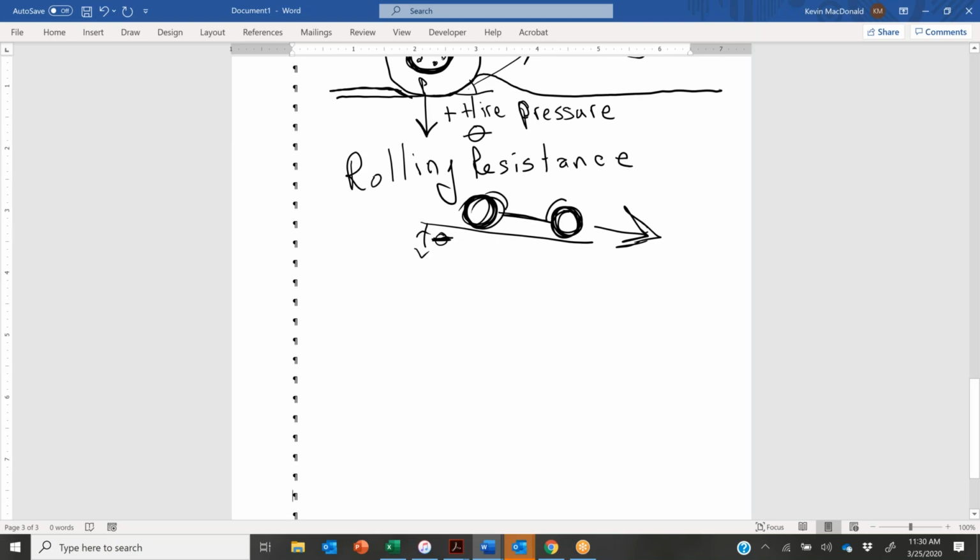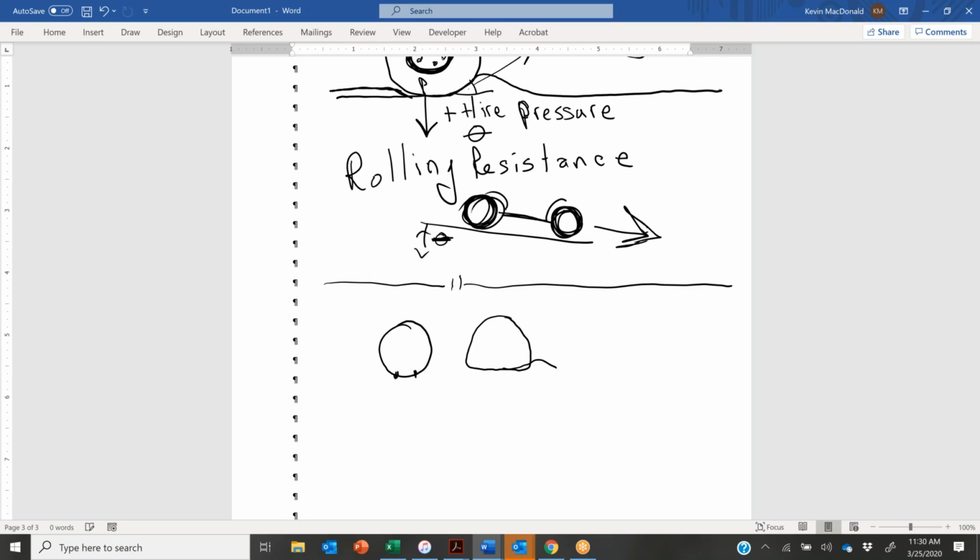There are people that do, and in fact, most of the ready-mix trucks that our friends operate in the world took this traction from the military. So if we have a high pressure tire, we have a low contact area. If we have a lower pressure tire, then we have a higher contact area and we get more traction. Low pressure tire, high pressure tire.